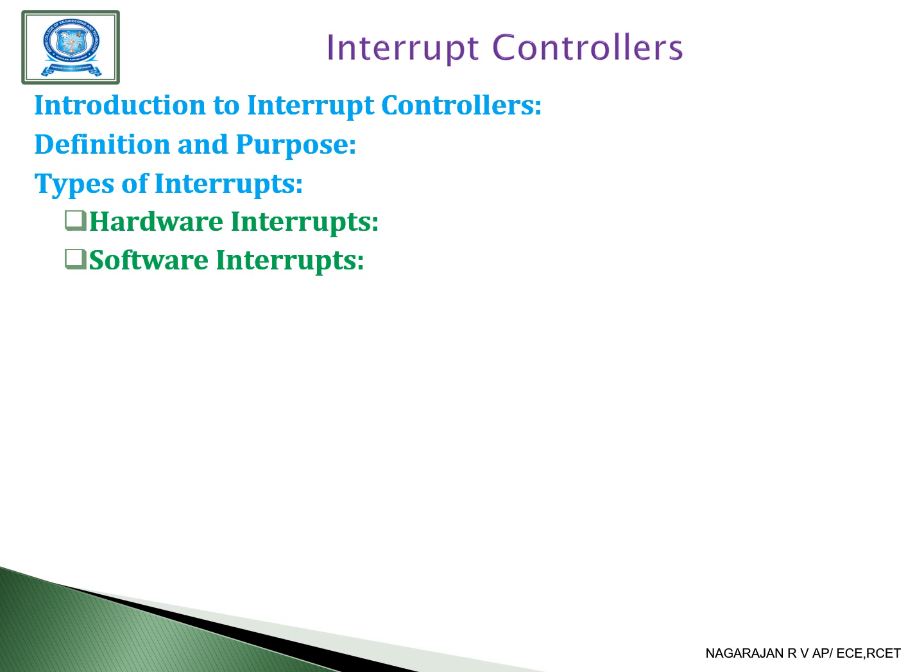A software interrupt is triggered by a software instruction within the processor. These interrupts are used to perform context switches, system calls, or to handle specific software-defined events. The next one is a maskable interrupt. This type of interrupt can be disabled or masked by the software to prevent it from being processed by the CPU.